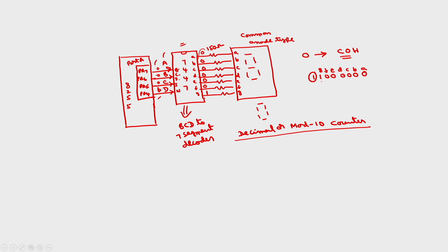Here basically you have to give only 4-bit BCD. So, you assume the same locations: move AX comma 5000, move DX comma AX. Then these connections are, we are assuming we only have to give output as BCD. Here also you have to program all ports as output ports in mode 0. So, out FFH comma AL. These two instructions will program all the ports as output ports in mode 0.